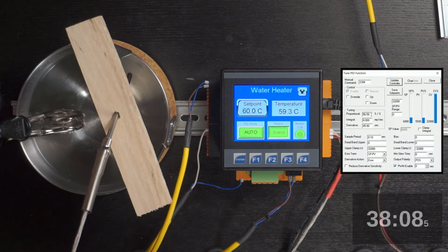basically what I'm saying with this long-winded description is the suggested coefficient of 56.5 is pretty close to 64, so I don't think bumping it up to 64 is going to make much of a difference. It might save a few seconds in heating the water from the beginning, but it might have a negative impact on how tight we are or our overshoot. So I think I'm going to leave things alone.